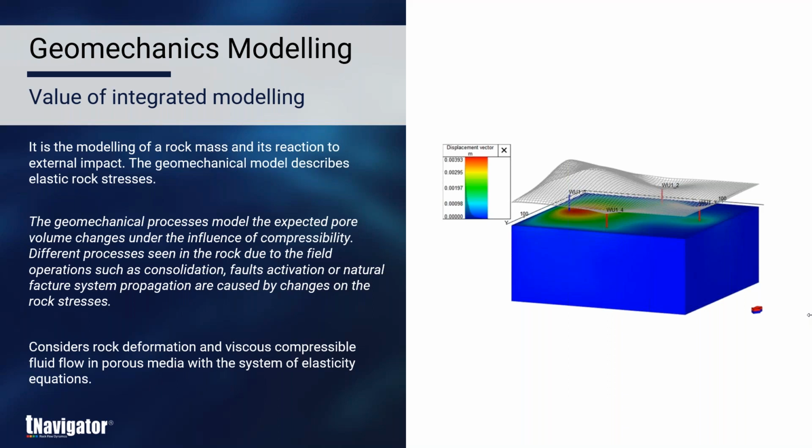So simply, we have capable software modeling the full field geomechanical features, fully coupled at all times with the simulator itself. We have two elements. We have the finite element calculation using the grid split into 6 tetrahedra, and then we have the finite difference model, all in one. The connection between them is continuous: every single time step we calculate stress, and we calculate the pore pressure and saturation changes as well. On the next slide, we see the type of approach.